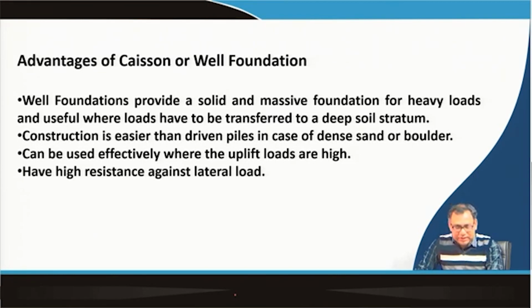The construction is easier than the driven pile in case of dense sand and boulders, and it can be used effectively where the uplift loads are high and has higher resistance against lateral load. So, that means here I can replace a group of piles or a number of piles by providing a well foundation, that is also one advantage.